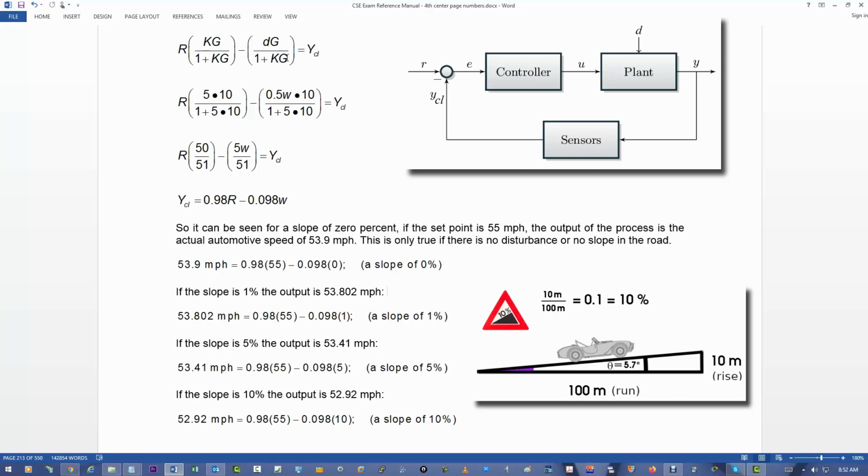Well, a controller gain of 100 is pretty high, and it's pretty unrealistic. That was the example used in the book. Typically, you want to have a low gain or it's going to oscillate on you, especially when you have a disturbance or a set point change. So what we do is set the controller gain, K, down to 5, leave the plant gain at 10, and redo this problem. You'll see we're not that far from offset. Like I said earlier, you'll get a little more offset from set point, but it won't be that far because it's closed loop feedback.